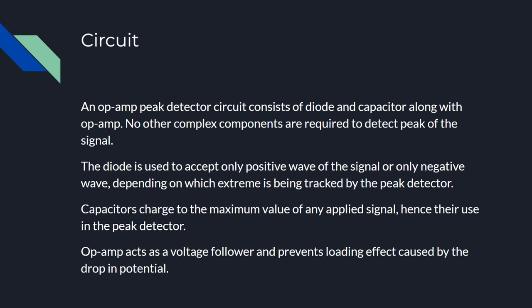When a component having some internal resistance is connected in parallel with the load resistance of circuit under test, the circuit conditions will be altered. The effective resistance will be the parallel combination of the two. And as we all know, parallel combination always gives lesser resistance than either of the two resistances. The voltage across this effective resistance will also appear to be less than the true voltage. This is known as loading effect.